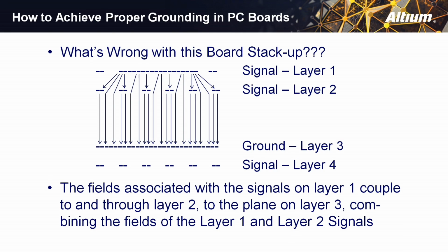Now, they don't have a tight coupling. If you're not concerned about EMI and you're only doing digital work, this kind of design is almost never going to cause you a problem, because the amount of energy coupling is way too small to cause signal integrity problems. That's why we got away with this kind of design for many years, because people didn't care about EMI until one point in our history when government started driving it hard.